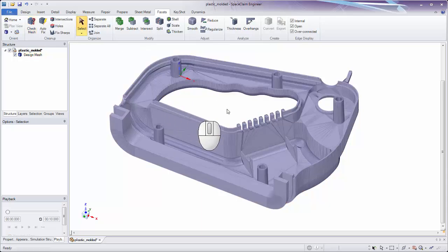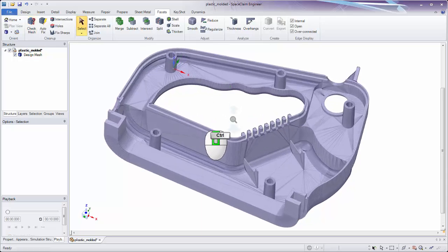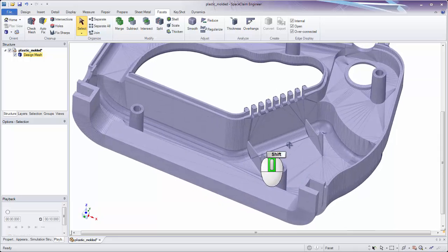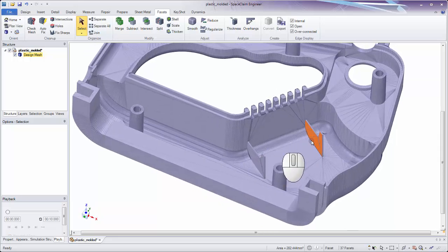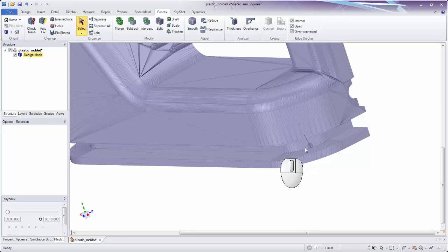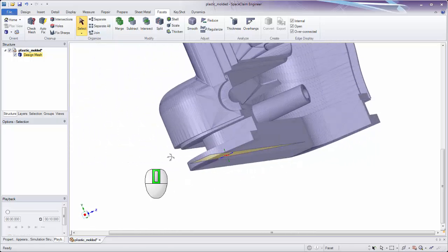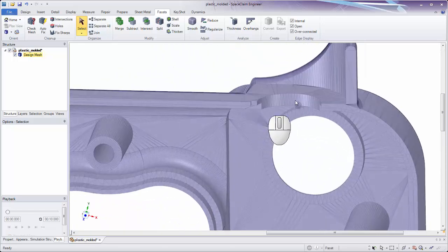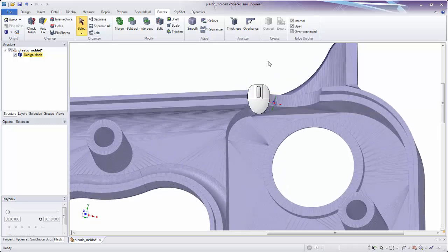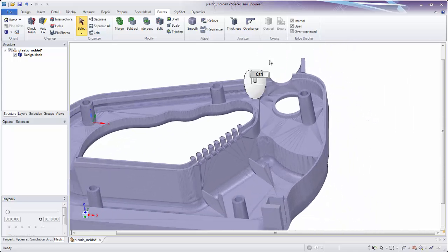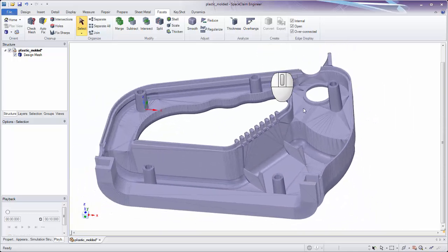But I'm going to go ahead and escape out of the check mesh tool and explain what we're going to do here today. We're going to take a look at copying and pasting individual objects like this standoff here. We'll take a look at copying and pasting just some individual faces, say on the side of one of these ribs. We're going to add a round to this area in here by copying and pasting some geometry and turning it into a regular solid. And last but not least, we're going to remove an area that isn't quite easy to fill in, where the holes tool doesn't quite do the job we want after deleting some faces, and we'll take a look at copying and pasting some edges and see how we can work with those.